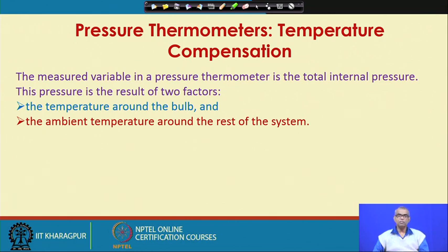But we basically want the pressure to be a function of the temperature around the bulb alone, so that I can get a correct reading of the medium. But the pressure build up depends both on the temperature of the medium, which is the temperature around the bulb, and the ambient temperature around the capillary as well as the pressure spring.